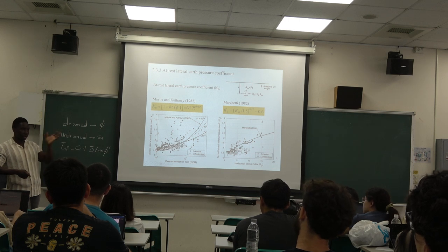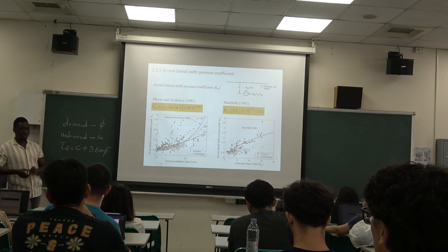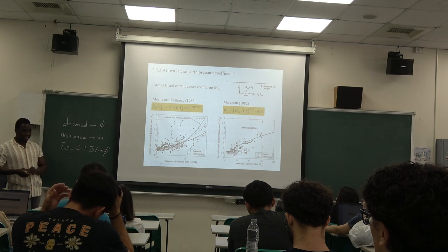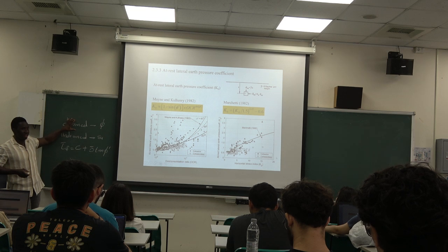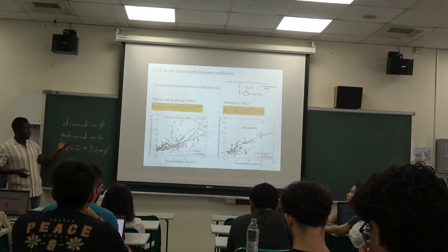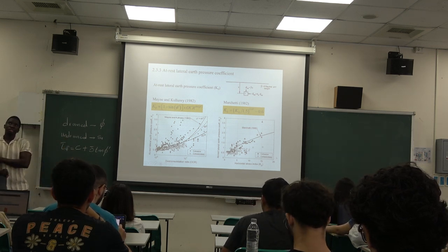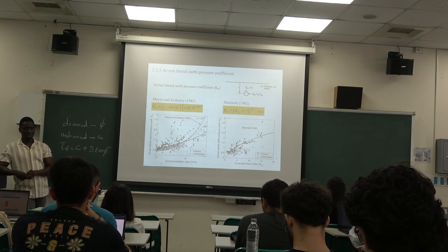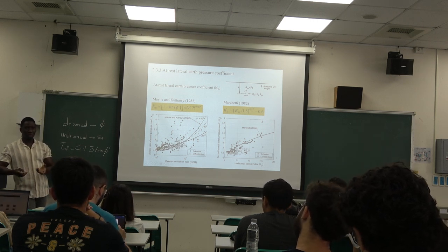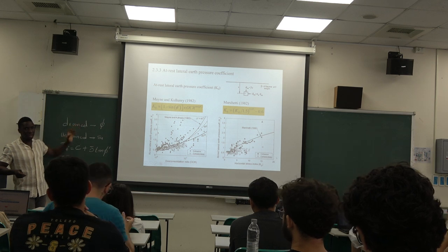Okay, so if you get a good understanding of what is drained and undrained, it will make a lot of things easier for you in the future. But if you still confuse these two, then it will be a little bit problematic for you. The concept is quite straightforward and simple. So you try to just visualize it and make sure that some of these key ideas stick to you. Because these are some of the things that even when you go out to work, you will use them, right? Most of the calculations you do, nowadays we have computers. We just input the parameters in the computers to do the calculation. But how do you ensure that what you are doing is right or wrong? You need to know what you are doing. Am I doing undrained analysis? Am I doing drained analysis? Okay?